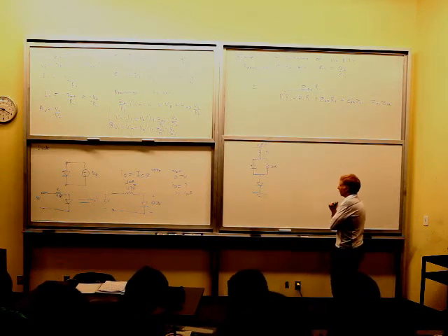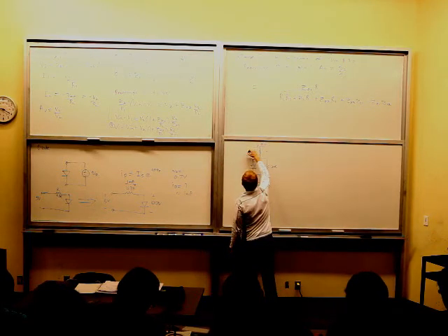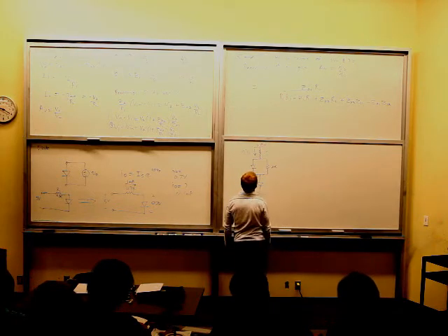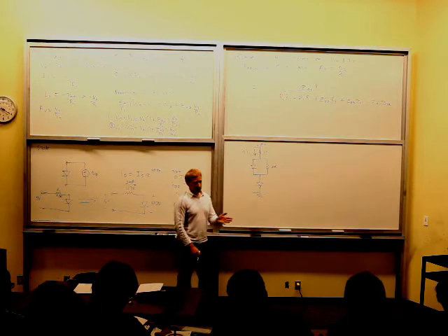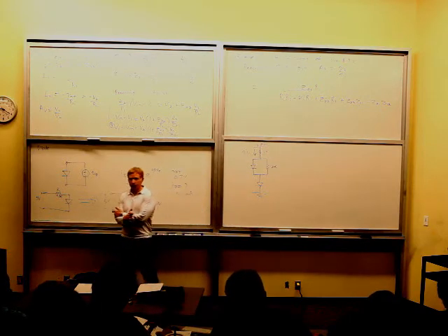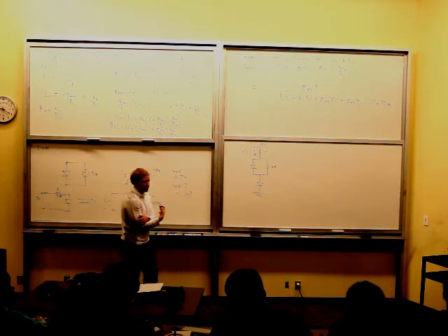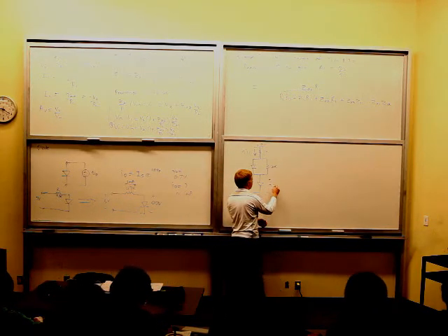So how would I solve this? And the question would be something like, what's the current through here? What is I1? So here's what you do. In all these questions, same for BJT, same for this, you always just assume that it's forward biased and that it's 0.7 volts, okay? So right away, I'm going to assume here that this one is 0.7 volts, right?